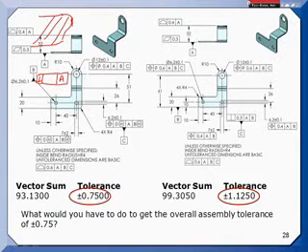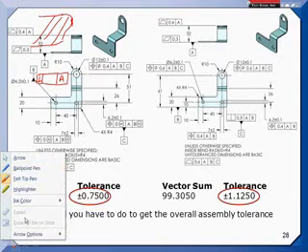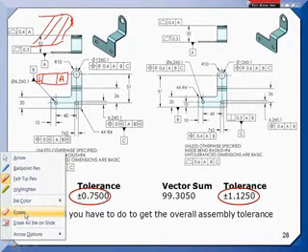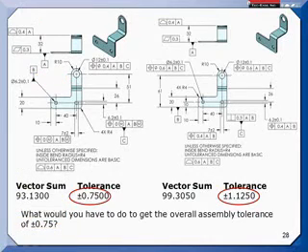Okay, Don, so then holding on to that same frame, on the right-hand side drawing where they were picking the outside edges of the surface, datum feature B is now the lower part of that bracket, and there's no control back to datum feature A. Is that the same thing? Yeah, it's so thin. Oh, okay, because of the thinness of the part?